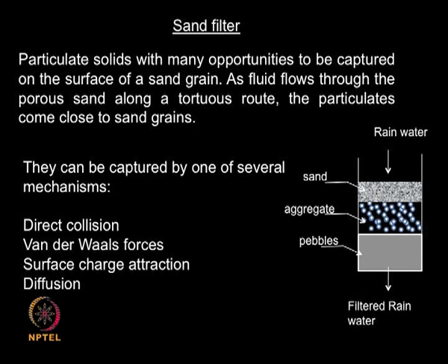So how do they get captured? The direct collision between these particles or wasteful material with the sand or pebbles present. There could be van der Waals forces, there could be surface charge based attraction, there could be diffusion and so on. So different types of interactions take place as the fluid moves through this depth filter, and the solids in the fluid get captured or removed.